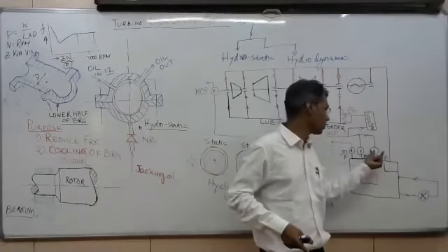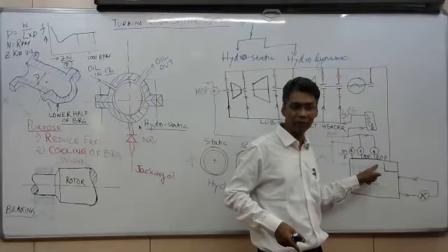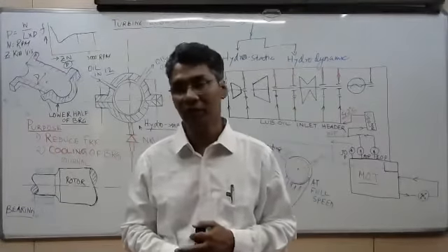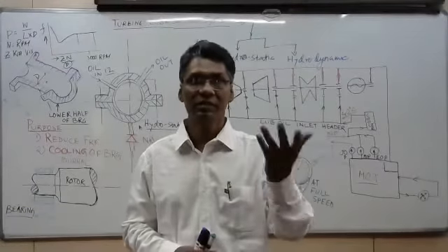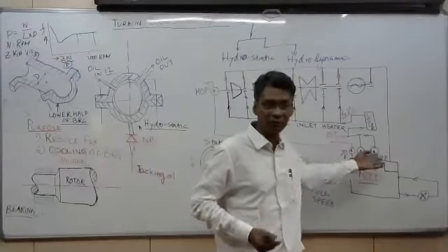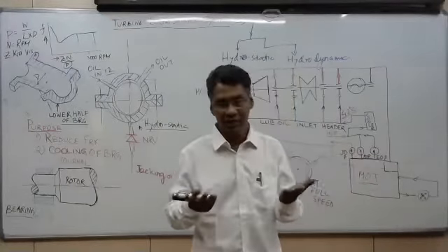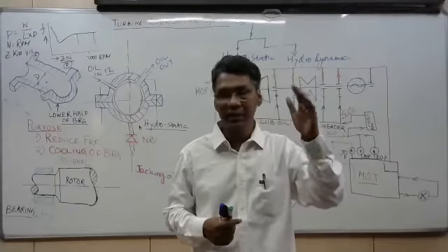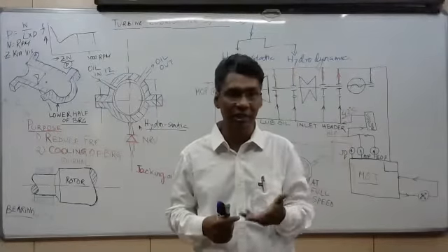For turbine protection we provide an emergency oil pump, a battery operated DC oil pump, which runs on protection. If power is not available, the EOP supplies the bearing oil, so at least some lubrication takes place and prevents damage to the turbine rotor and bearing surfaces.